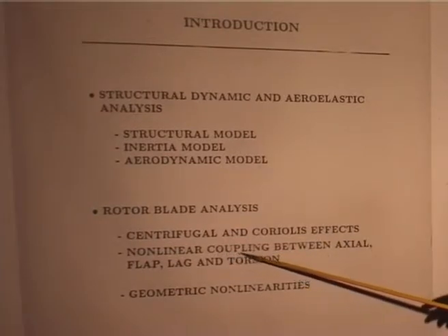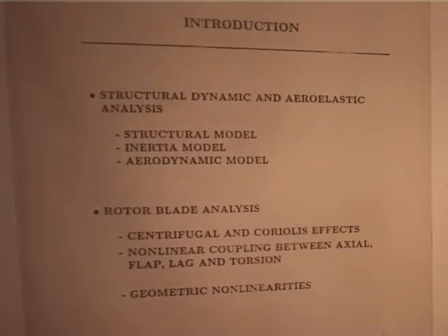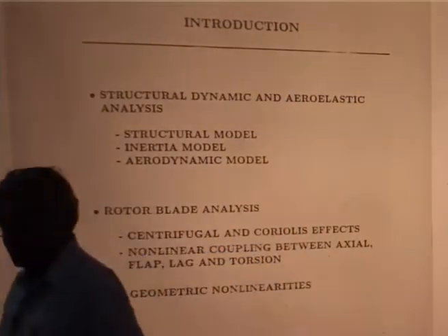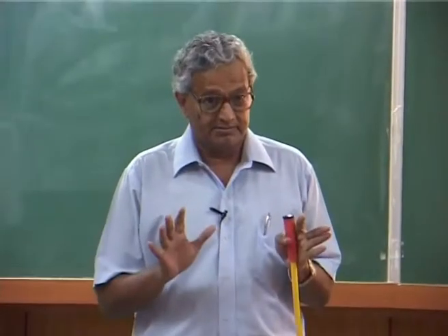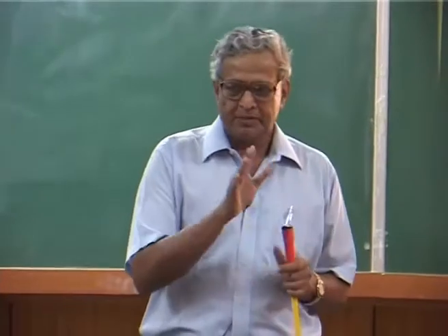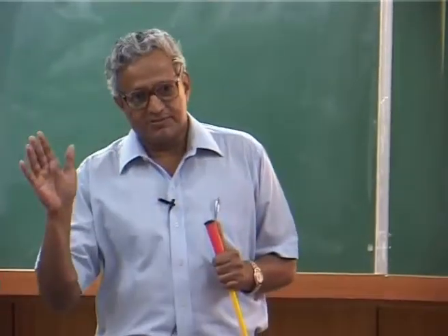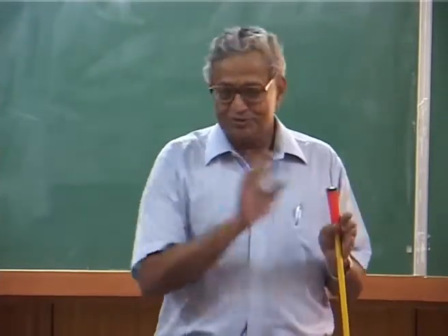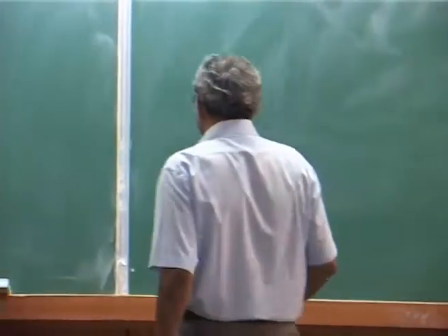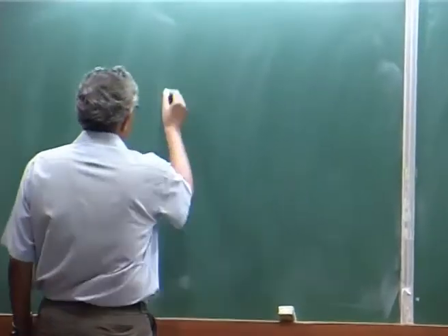Then of course, you will have nonlinearity, which comes because of axial deformation. Okay. Because of the centrifugal force, how do you account for it? In earlier days they were taking it in an approximate manner, but if you systematically derive the equation, you will find it is a nonlinear equation. What type of nonlinearity is it? Strain to displacement is nonlinear. Please note, strain to displacement, that is one nonlinearity which is called the geometric nonlinearity. Okay.